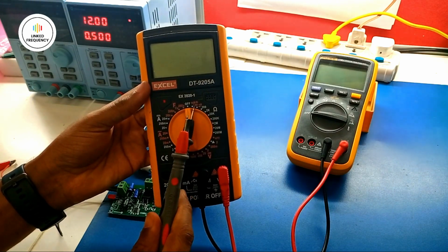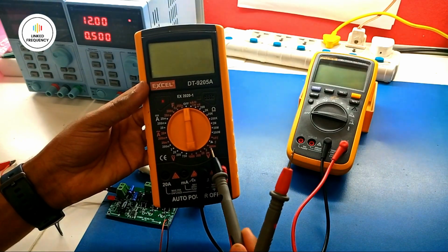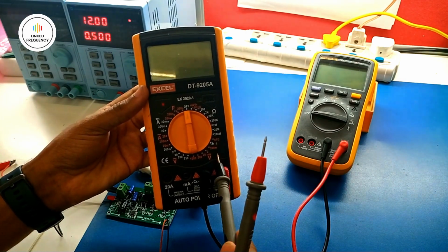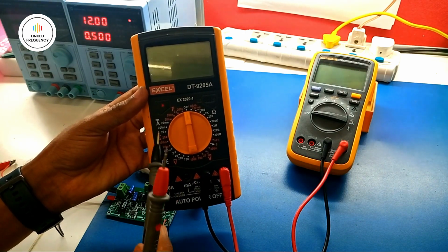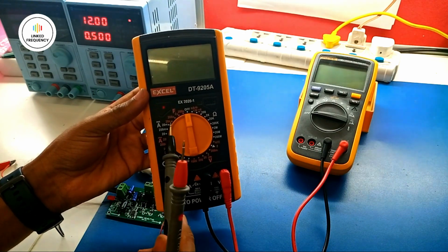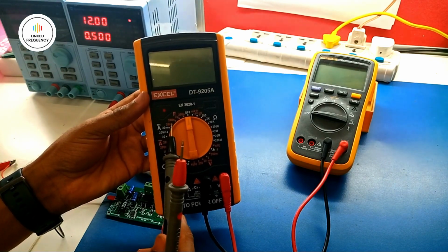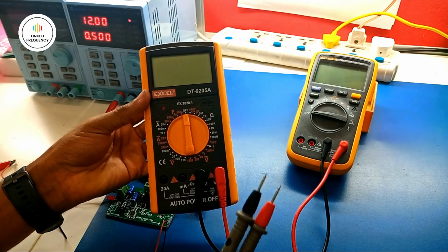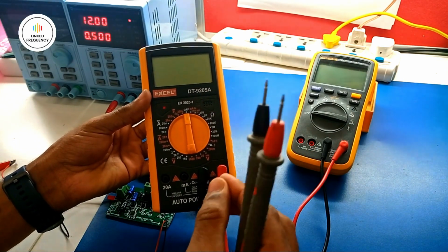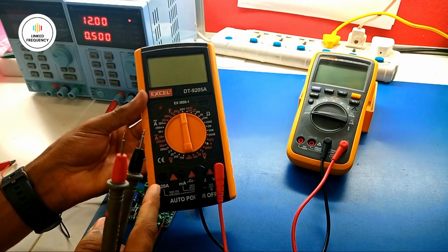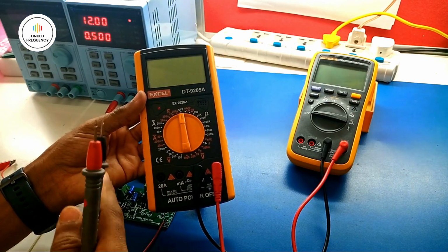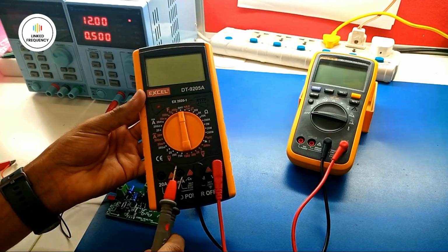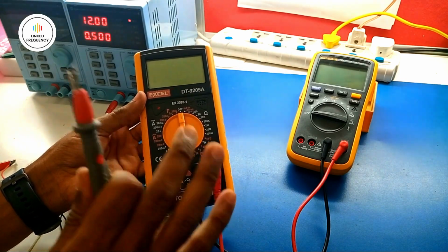We have an option of measuring the resistance here, and we have an option to test the diode and also the transistor here. Also we have an option for DC voltage, AC voltage, AC current and DC current measurement. Along with this, we can also see farad, which is nothing but capacitor measurement, in this multimeter. So we have to remember that this red color probe has to be unplugged and plugged to the milliampere or ampere plug to measure the current. If you keep it here and try to measure, it is not possible. And if you keep the plug at current rating and try to measure the voltage, it is going to damage the multimeter.